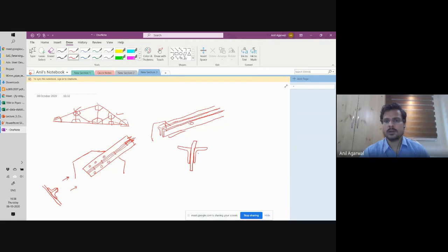So the centroid of the two angle system is somewhere here, right? And the gusset plate's centroid is also somewhere here. So when you are applying the axial load, it is acting right at the centroid. So then the issue of lateral torsional buckling or flexural torsional buckling is resolved. It's not really required. So you can consider this as a flexural system. Pure flexural buckling can be considered.